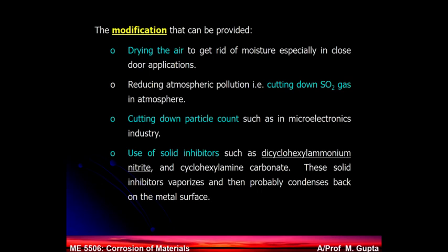The dust particle count has to be less than a certain minimum level. Very high, stringent requirement. The size of dust particles ranges from about 5 microns to about 20 microns, and the distance between these channels is less than 15 microns. So if you have dust particles in the atmosphere, they can sit on two channels, short circuit that circuit, and the system fails.